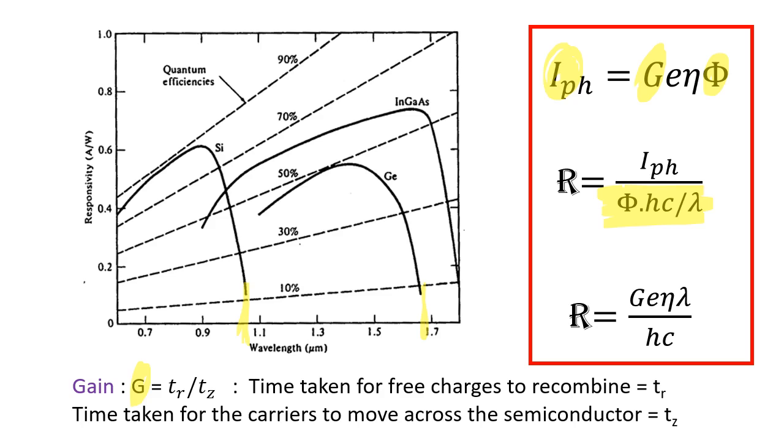On the other side, there is a time scale which is telling you the time required for the carrier to move across the semiconductor block, which is connected to the external circuit, the time required for it to travel from one end to the other, essentially, because that limits how quickly I can register something as a signal in my external circuit, right?